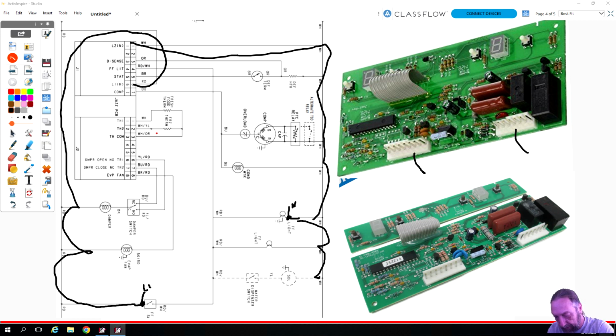I'm gonna try something here. Hold on, I'm gonna try to feed it one more time. The board's not lighting up here, as you guys can see. I turned on the power switch. I'm gonna turn it off. I'm gonna take this red one off and put it back in here on this third wire red. Nothing? Board still don't light up? Let's check my neutral.